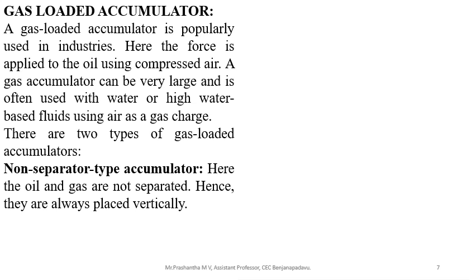The principle of working here is Boyle's law. It states that for a constant temperature process, the pressure of a gas varies inversely with its volume. When the gas is compressed to half of its original volume, the pressure of the gas increases to 2 times its initial pressure.